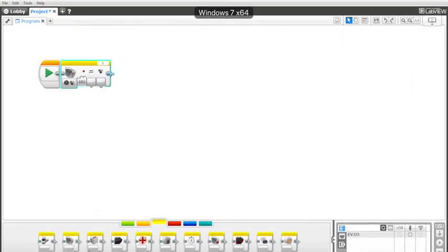Okay, next sensor we're talking about is the gyro sensor. So gyro sensor, by this look and feel, is used to detect the robot rotating on this surface, displayed as the rotational sign. So it can measure. Of course, the first thing we need to do is to specify which port it's connected to. If you specify port 4, for example, then you make sure your gyro sensor is connected to port 4.